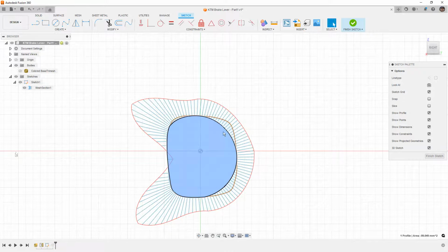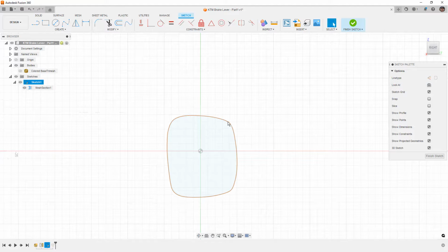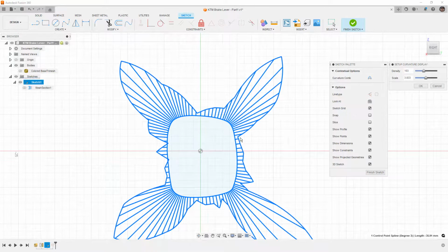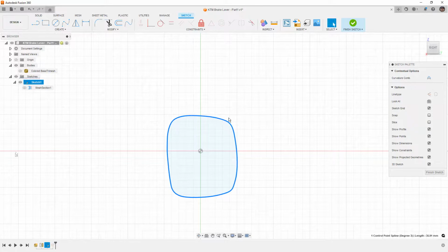Now this one was the plus or minus 1 millimeter. The version that's plus or minus 0.1 is, again, problematic because it's got a lot of these spikes. Now, does this matter in terms of the part that we're creating? Yes, 100% it matters, because downstream, you're going to have surface imperfections or quality issues, especially once we start to take this and try to do things like loft between a prismatic shape. If we have an extrude with fillets on the corners and we try to loft between this and that, all these little irregularities in the surface are going to start to come out. Because of that, we need to be extremely careful when we're creating these mesh sections and using these tools and these tolerances.